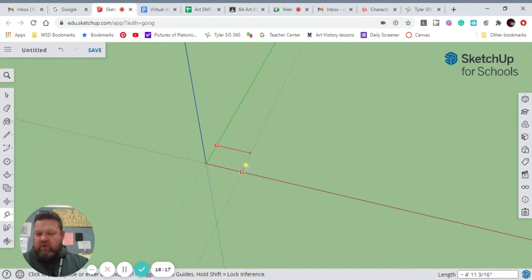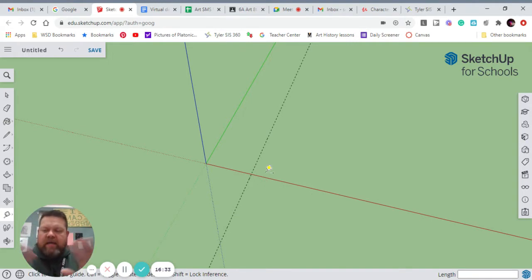So here's what you can do. Let's change that measurement. Let's say I want it to be 5 feet wide by 10 feet tall. So I'm going to grab my measuring tool. I'm going to pull this out and I'm going to just let go of it. Before I do anything else, I'm touching nothing else. I'm going to type in 5, and then I'm going to hit the apostrophe button. It's going to give me a single tick mark, and that stands for feet. Now I'm going to hit the enter button.